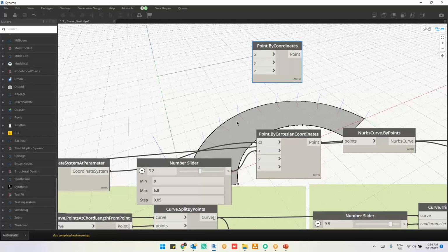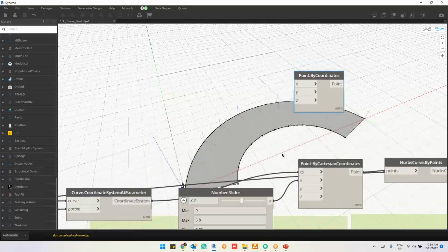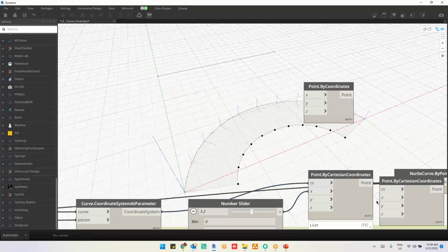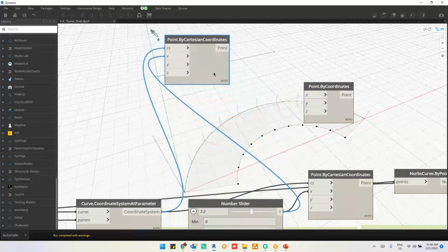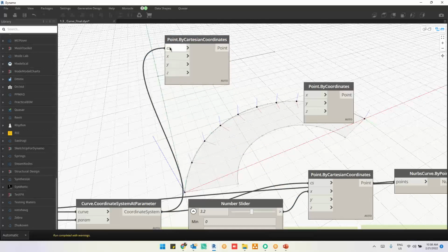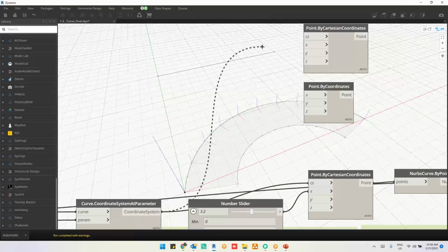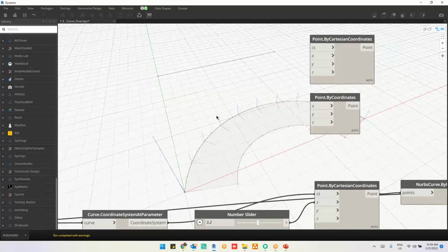Well, for example, let me copy this. If I need a coordinate system, I will need a coordinate system here. Autodesk.DesignScript.Geometry.CoordinateSystem.ByOrigin. By default, it is considering ByOrigin. Where is the ByOrigin point? This is going to be the ByOrigin point.